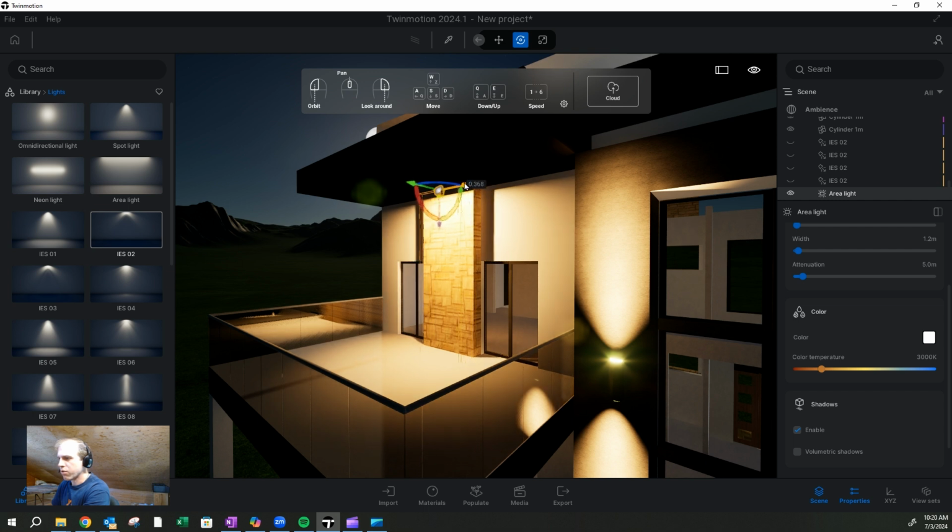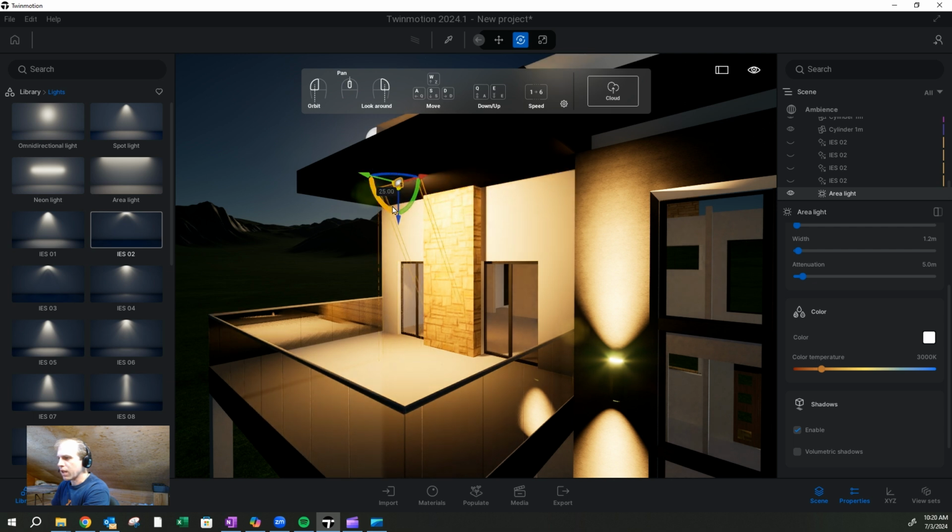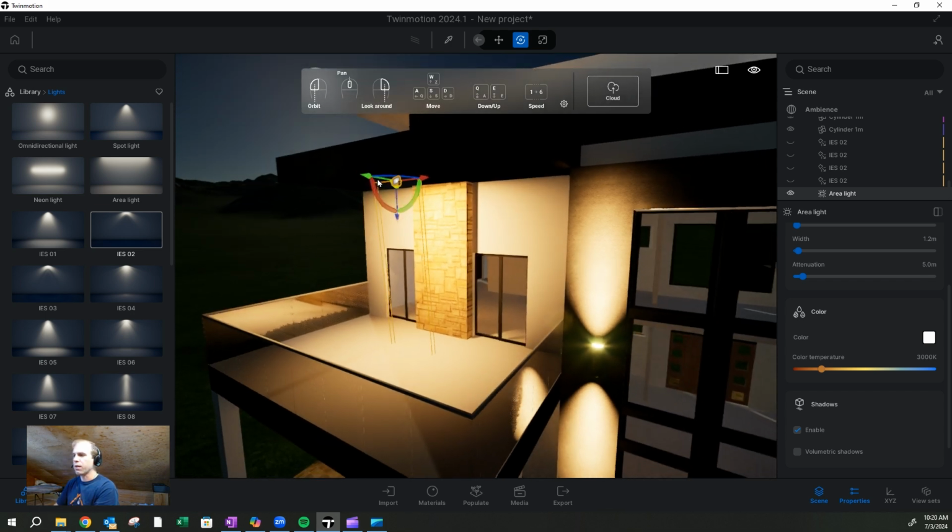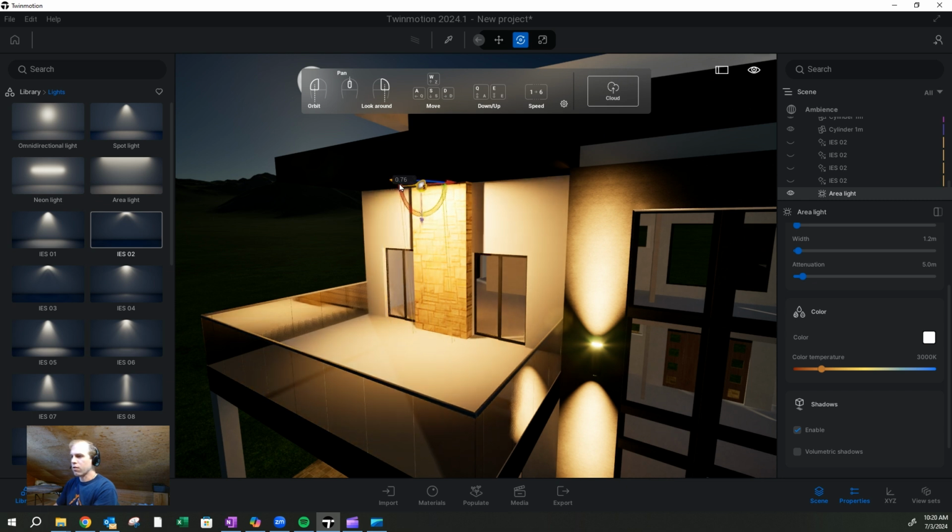A graze light would be placed closer to the wall. A wall wash would be more backed off and aimed towards it, creating that uniform light. But a graze is usually a narrower beam and it gets more light. It shoots out kind of like water out of a garden hose. If it's all open and no pressure, then the water's not going very far. If it's tight and narrow, the water shoots a lot farther. And water is a wave. Well, guess what? Light is a particle and a wave too.